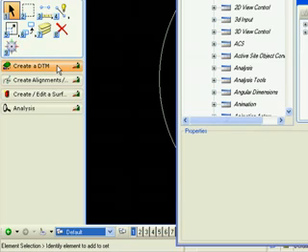In civil design, I'm using workflows to complete my tasks. A workflow is simply a collection of tools in a specific order for the user to gain familiarity with to create or complete a task. So in this workflow, to complete a civil design, I first create a DTM. I next create alignments. Next, I create or edit my surface. And finally, we complete analysis.